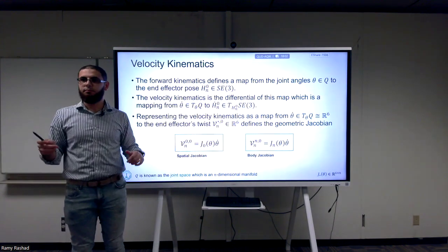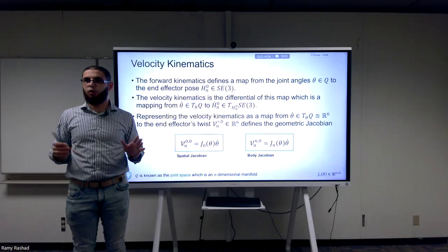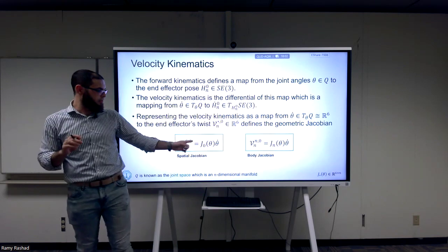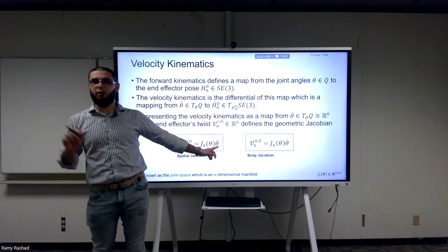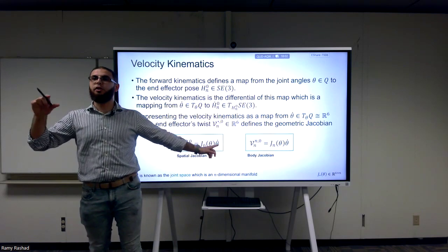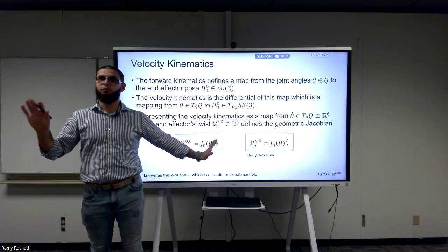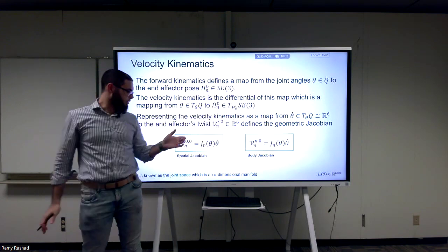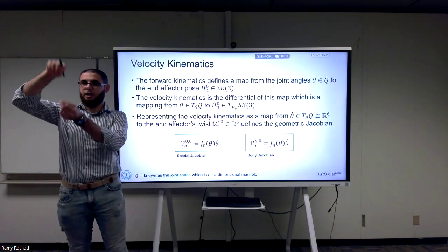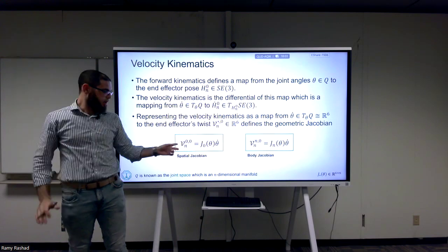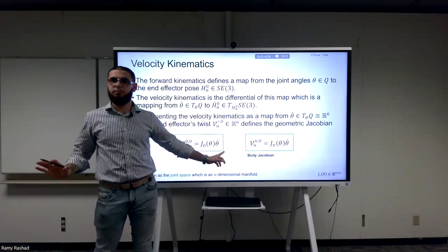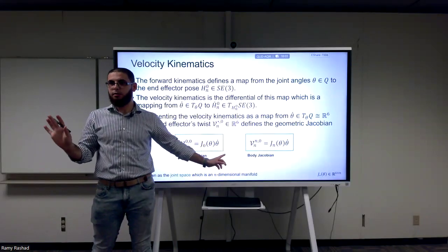Easy? It's different from what omega here? There's no omega here. Again, the omega, you mean the 3 numbers here? But we're talking here about the angular rates of the joints, which is a velocity. But again, you have a lot of things that are moving now. So the twist has 6 numbers. The first 3 on the top is an angular velocity of frame n with respect to frame 0 expressed in frame 0. But this is something else. They both have the units of rad per second. That's correct, but they're something different.